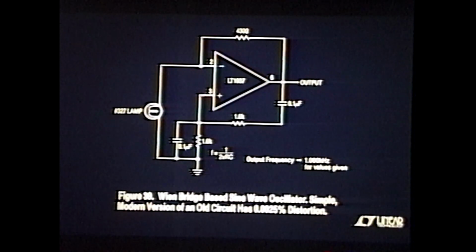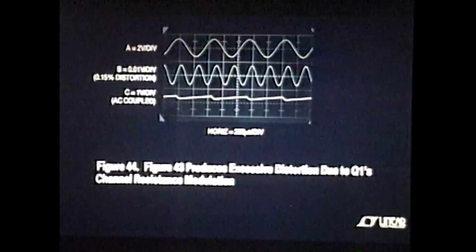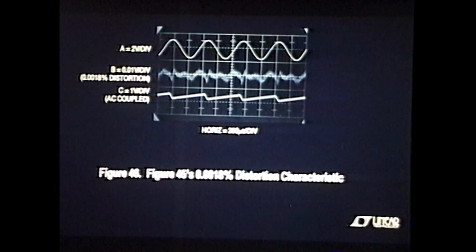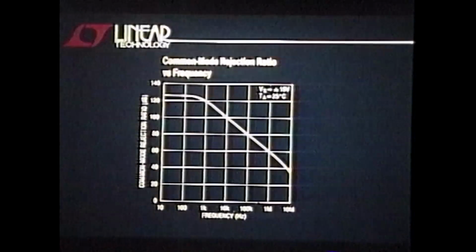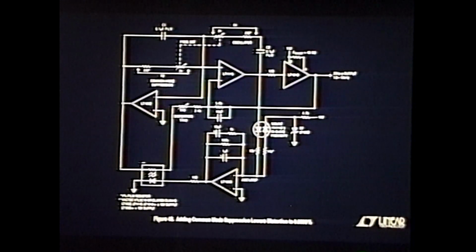So what I want to do is measure the voltage between these points, and as a result of that measurement, drive this point to maintain those points at 0. So here's what I'm going to do. Instead of a hopeless gain matching exercise, I'll fill up that hole with this op amp.